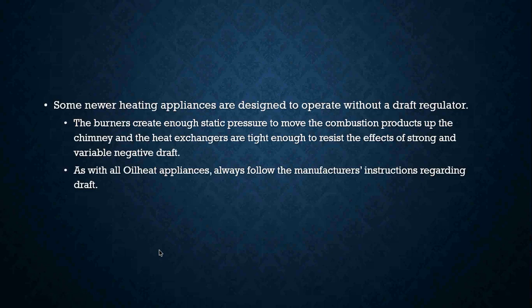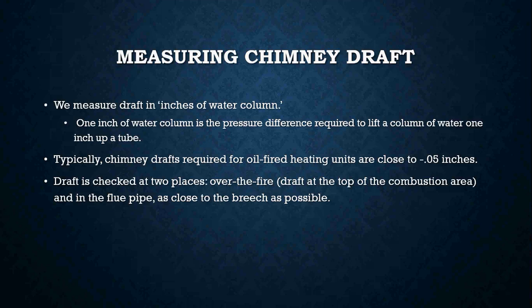Some newer heating appliances are designed to operate without a draft regulator. The burner creates enough static pressure to move the combustion products up the chimney, and the heat exchangers are tight enough to resist the effects of strong and variable negative drafts. So as an oil heat technician, always follow your manufacturer's instructions regarding draft and where to place your draft regulators.